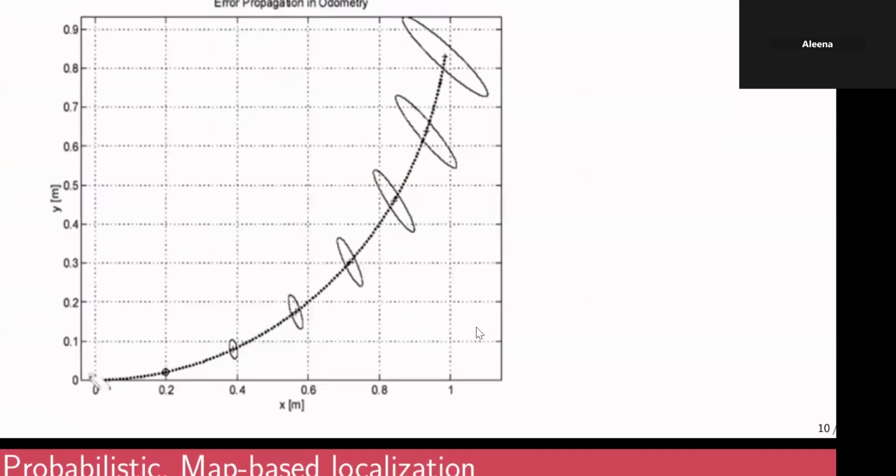So from here to here, there is no insight from the external sensors. What you can do is take a measurement here. When the robot is here, you are getting a measurement from the sensors. You exactly know the position of the robot, and you can compare that with the predicted position. And if there is a big difference, the robot can easily do the compensation.